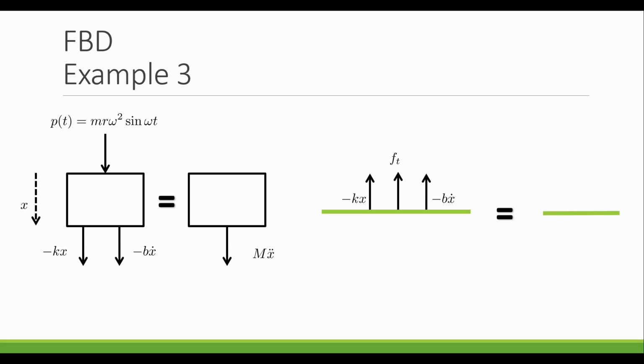So really what we're looking for is that F of t. What is that kind of returning force? That's the total force that's going into the floor there. So from the right-hand picture, I'll skip a couple of the steps here. But after we do a Laplace transform and we do that equation of motion, we get the force in the floor. We get the relationship between F and X from this free body diagram is K plus Bs times X.